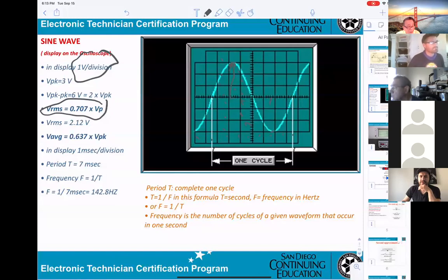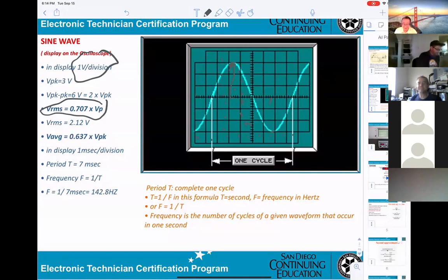You want to know how do we know VP, right? Just VP, the one right next to where it says RMS. The RMS equals 0.707 times VP. It's the same thing as VP. Okay. VP means V peak. Okay, thank you. Yeah, you get VP, then you can get the VRMS. The thing is, when you're doing the lab, then you have to measure.